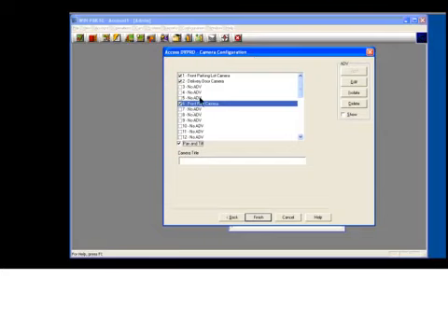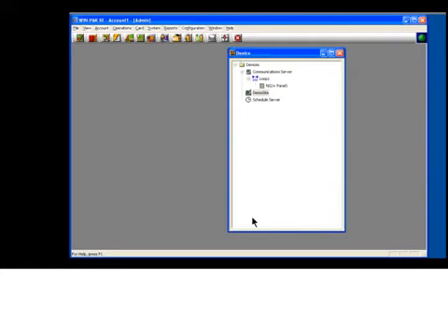There's other cameras on this DVR, but these are the only 3 that I really want to tie in at this point, because these are the only 3 that are located somewhere near the readers that I'm going to be tying them to. At that point, we hit finish. We're done. We've just integrated our DVR with the Winpak software.